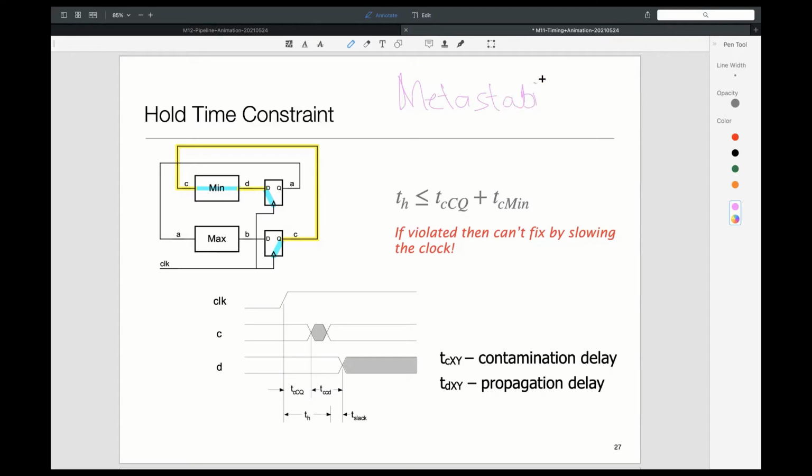If you're truly unlucky, metastability failure can happen, in which case the flip-flop goes into a non-digital mode. It basically hangs at values which are illegal values from a digital perspective. That's truly, truly bad. There's nothing you can do. You just repower up.